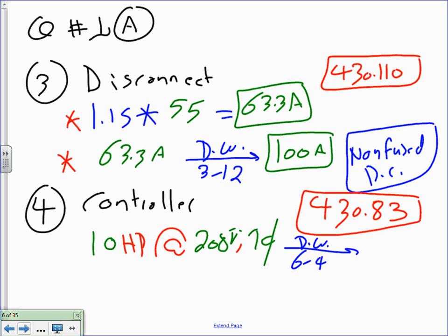You're right. It's hard for us to think like you. Think of 208 as single phase. Table 430.248, single phase, 208.